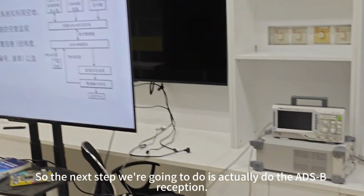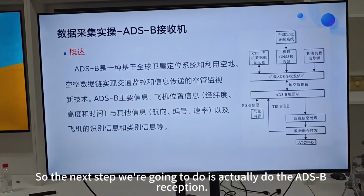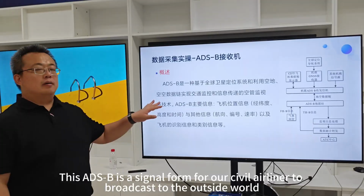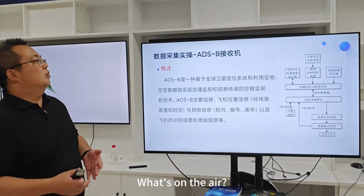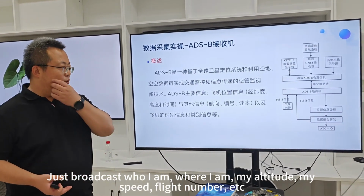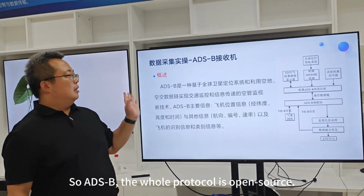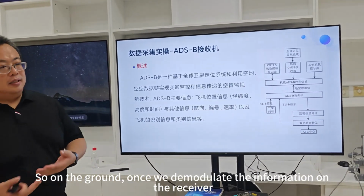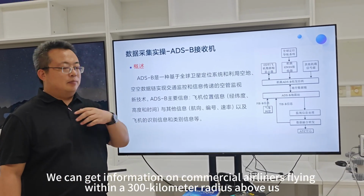So the next step we're going to do is ADS-B reception. ADS-B is a signal form that our civil airliners broadcast to the outside world. A commercial airliner keeps broadcasting signals. What's in them? Just who I am, where I am, my altitude, my speed, flight number, etc. The whole ADS-B protocol is open source. So on the ground, once we demodulate the information with the receiver, we can get information on commercial airliners flying within a 300 kilometer radius above us.